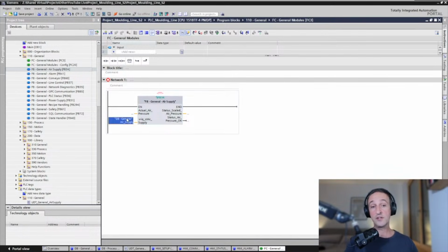You know, this structure would also be tagged up in your HMI. By the way, you can do that as one full structure, so just one tag that you need to add to the complete structure. That's another advantage. So in your HMI, you don't need to put a separate tag for each of these individual tags. You just add the complete structure as one thing in the HMI. So parameters, buttons from the HMI, that comes straight into the block. It's like a gateway, so the block reads and writes to the structure.